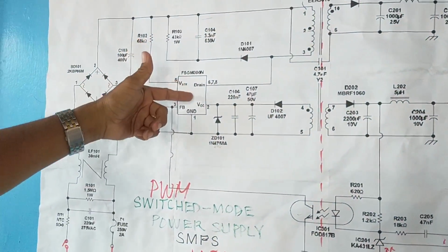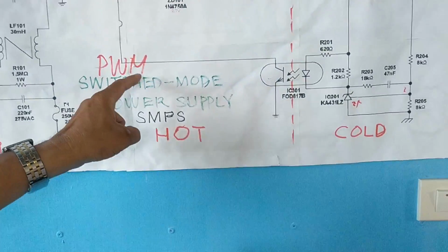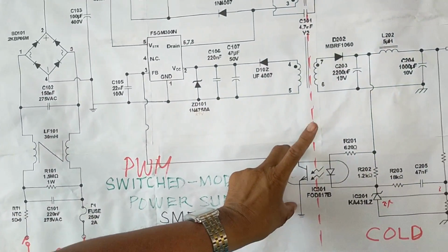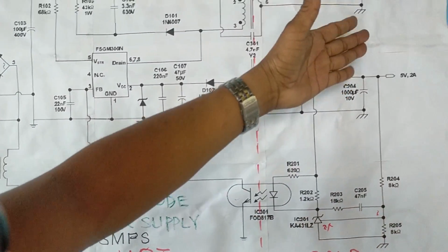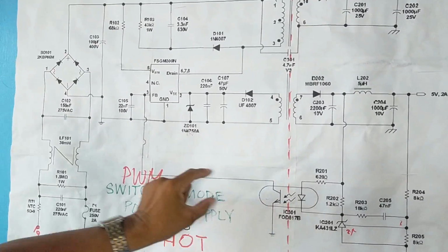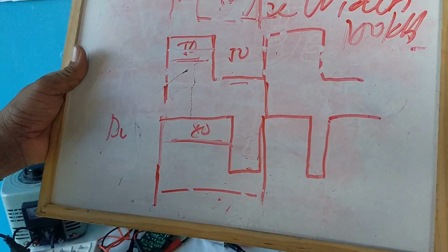So that is now the frequency here. But the pulse width is modulated. Actually, pulse width is modulated, or the other term is varied, by the feedback signal. So it is now the feedback signal, which is transmitted via optocoupler, that will vary the pulse width here.